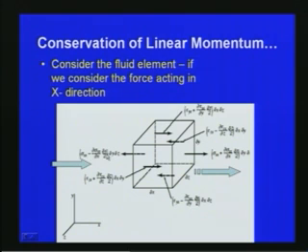So with respect to the normal stress, for this particular fluid element, on this face in the x direction it can be written as sigma xx minus del sigma xx by del x into delta x by 2, multiplied by the area of this face of the fluid element, delta y delta z.